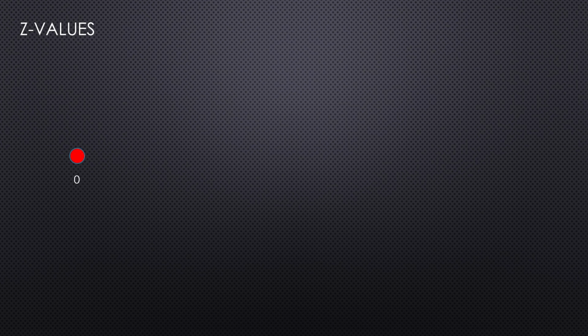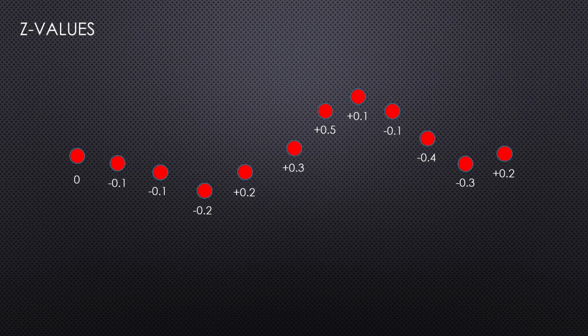Now if Q values are used in the calculation of FF, then you may be able to guess that Z values are used in the calculation of FL. Let's collect some points again. Again, these readings are 12 inches apart, and the Q's represent the curvature between 2 points, which end up being 24 inches apart. Each of the values that are being displayed are like before in that they are differences from one reading to the next.